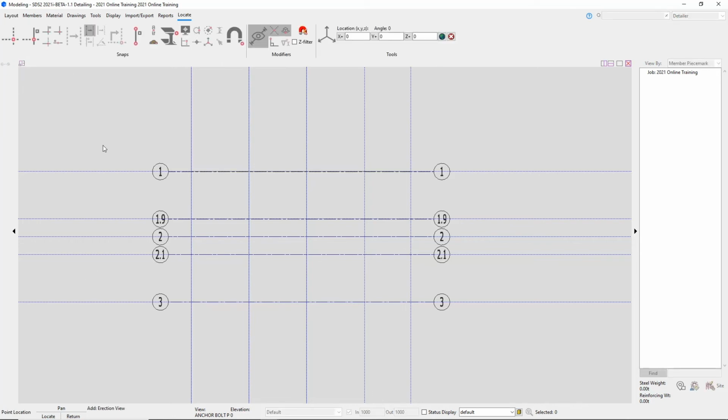The one thing I'll need to do here is change our snaps from base grid line to our intersection construction line, so I'll go ahead and change that. And for our vertical lines, I'm going to choose from bottom to top, so that we are looking left, or to the west. So I'll pick those 2 points.